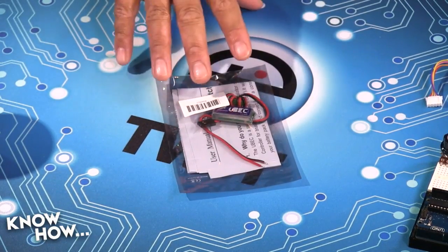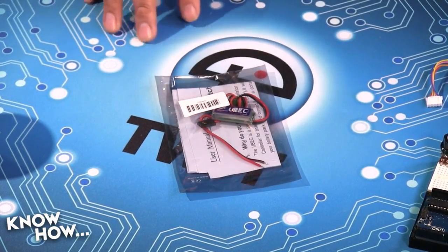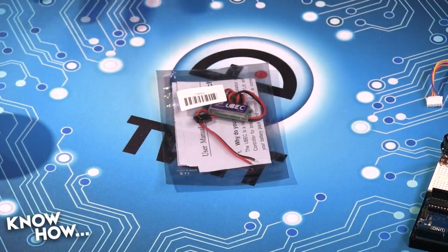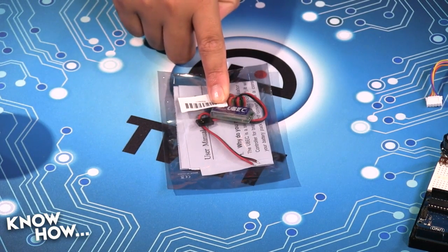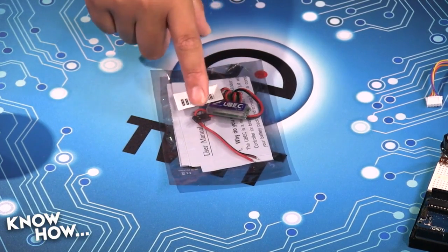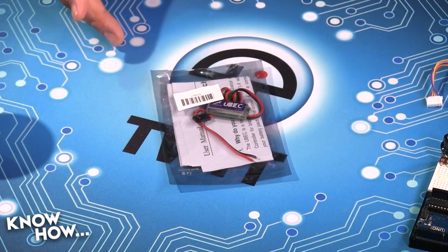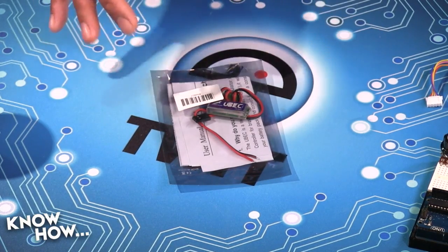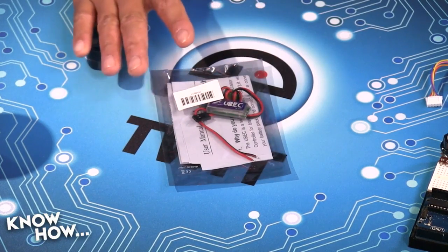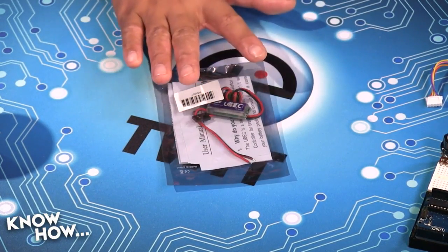This is, if you go to the side shot here, a simple 5 volt UBEC, Universal Battery Eliminator Circuit. You see this a lot in RC cars, but I've been using them for Arduino and Raspberry Pi projects because it's a very clean 5 volts, and this will take anything from, I think, 5 volts all the way up to 30 volts and convert it down into that 5 volts that I need. Okay. So I'll need some way to supply power to my stepper motors. I've chosen to do this.